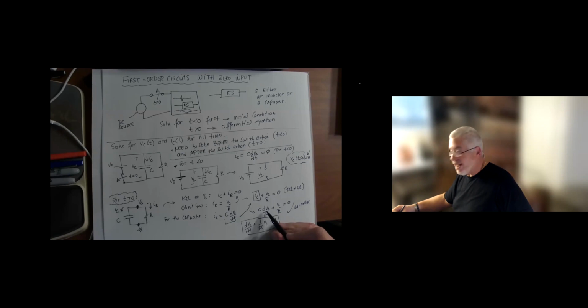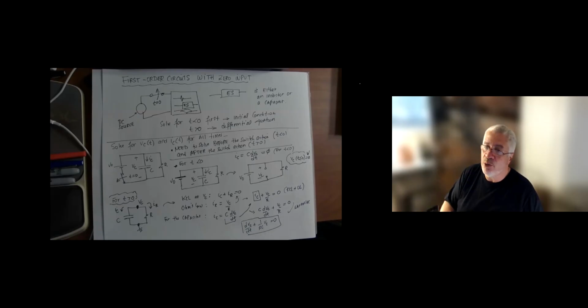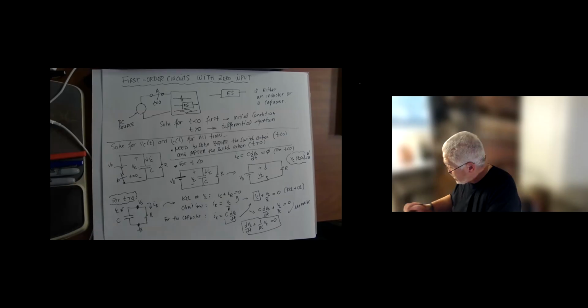And then finally, I normalize, dividing so that I get a unit magnitude for the highest order derivative. And I get here. So I'm hoping this shows you the process. You're going to see that over and over again for different circuits. I'd like to see your process. In fact, I'm going to write this down for you in an announcement. I'd like to see that whether you're doing nodal or mesh. It's going to be similar steps to what you see here so that you can come up with the differential equation right there.